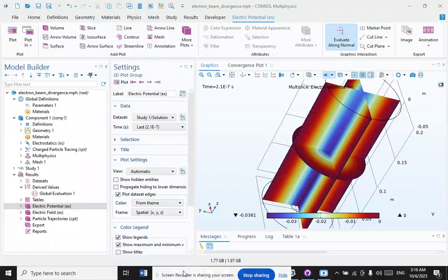Traditional weld modeling approaches neglect the fluid dynamics of the molten and vaporized region entirely, instead using phenomenological heat source descriptions to represent the complex physics involved in the fluid region and obtain thermal predictions by solving a simple heat conduction problem either numerically or analytically. These thermal fields are then typically used as the input for a residual stress computation.